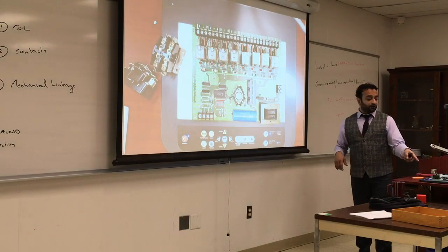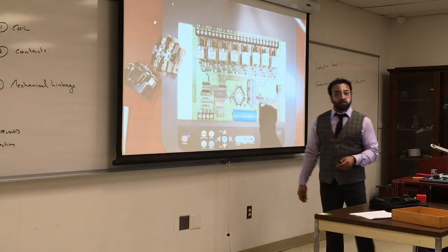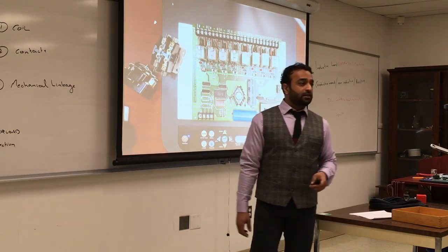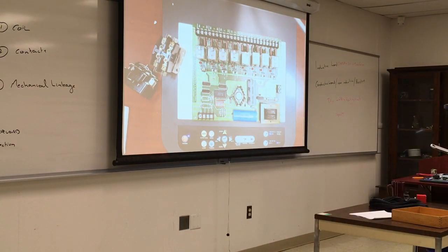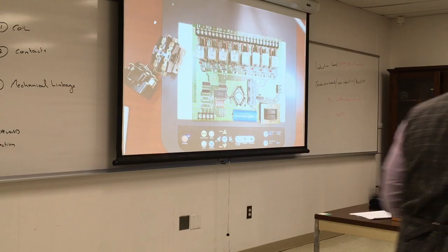So most boards of this type have a small fuse, and the purpose is that the fuse will take the hit before the board burns. Do not, under any circumstances, bypass the fuse by putting in a wire. A lot of people do that, and it's really not a good idea.